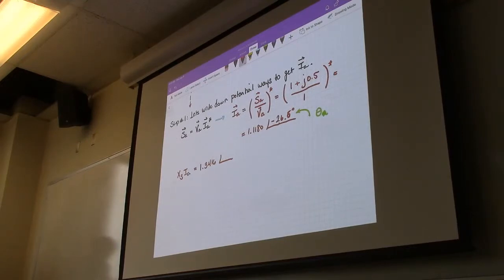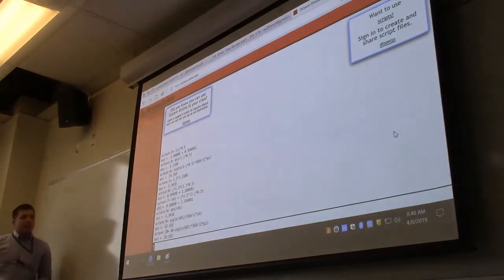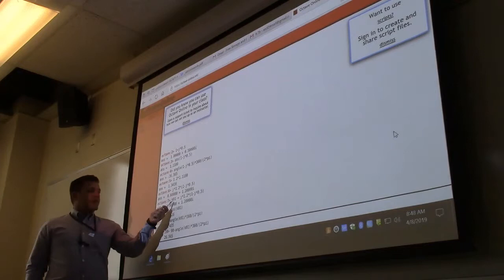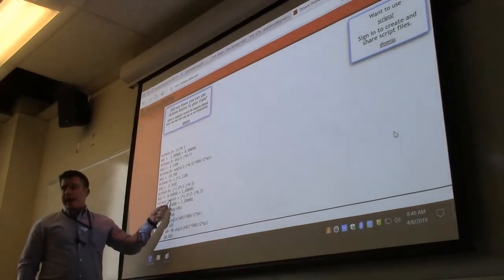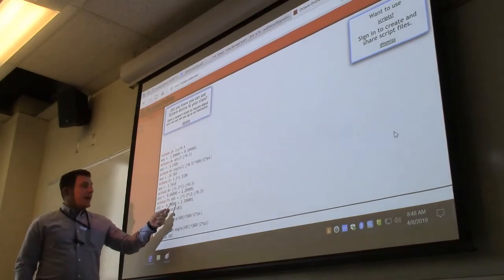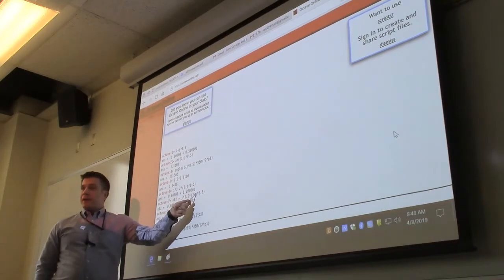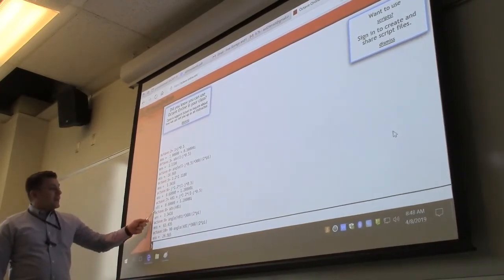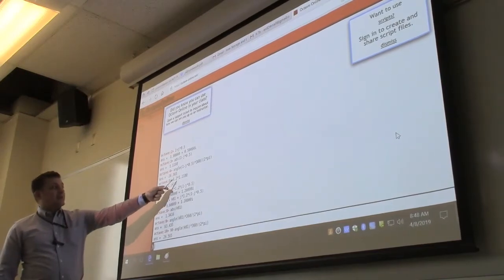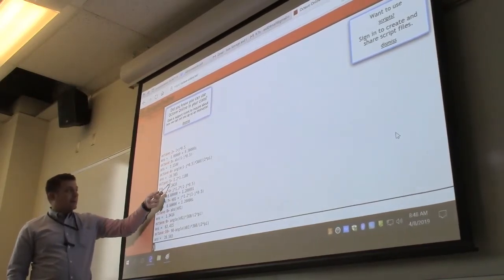I'll show you what I'm doing in a second. Okay, so if you look at what I did on the computer here, just to verify that everything is as we would expect. I calculate this value I call KO1, which is XS times IA, and that's equal to j times 1.2, this is our XS value, times the IA value. The magnitude comes out as we would expect if I just took the current and multiplied by 1.2.